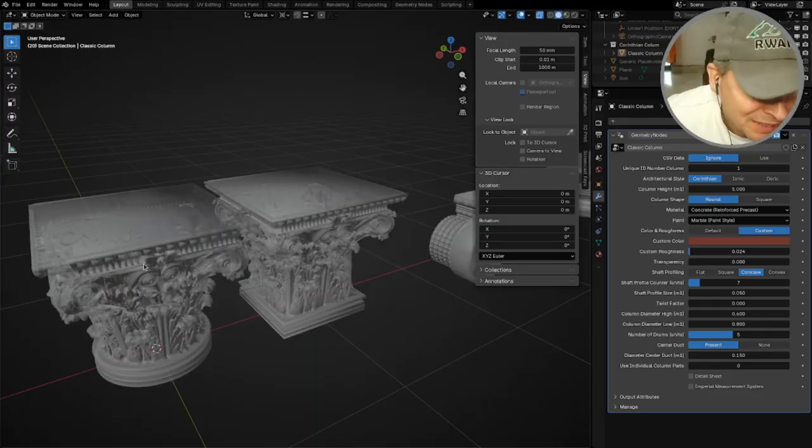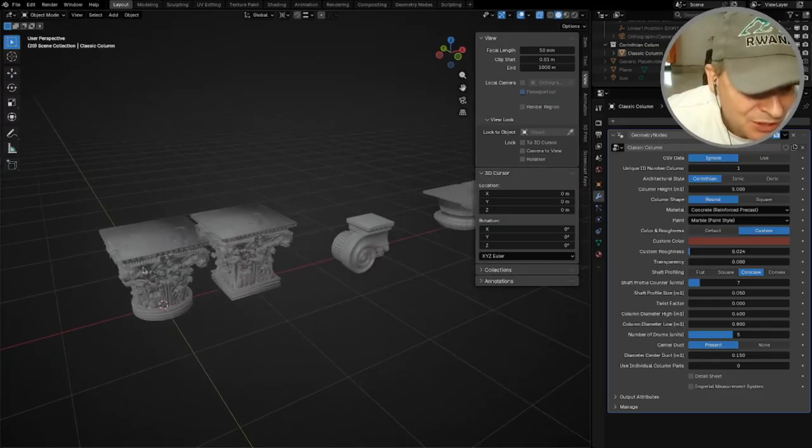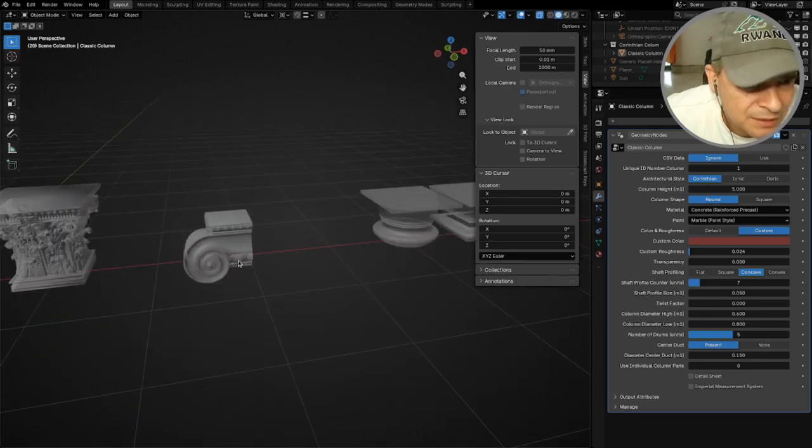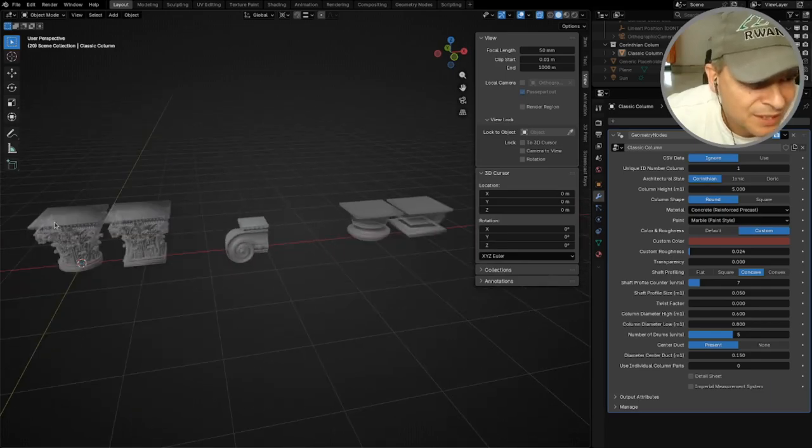And it's very nice to have manifold items to start with, because when you do booleans, and you do a lot of booleans, I will show you, manifolds are way faster than the other solvers for booleans. So if I want to cut, let's say, a hole, like to put a tube in this column head, then it would take like 5 times more time to do it if this column head is not manifold, compared to if it is. So that's just the way it is. I couldn't work around that. Actually, I started with 1/4 or 1/8, and I decided to bring it back like this.